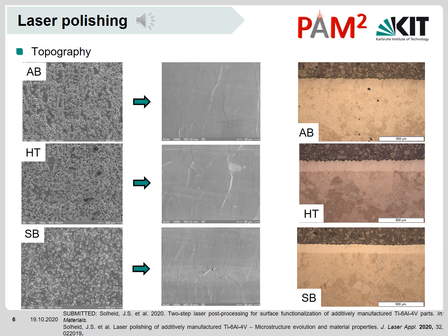The laser polishing successfully removed the surface asperities of Ti64 parts independently of their initial conditions. These images illustrate the surface topographies of laser powder bed fusion parts following three steps of the process chain: the metal additive manufacturing alone, the heat treatment for stress relief, and the sandblasting performed after the heat treatment. This slide also shows that significant heat-affected zones were induced during the process.